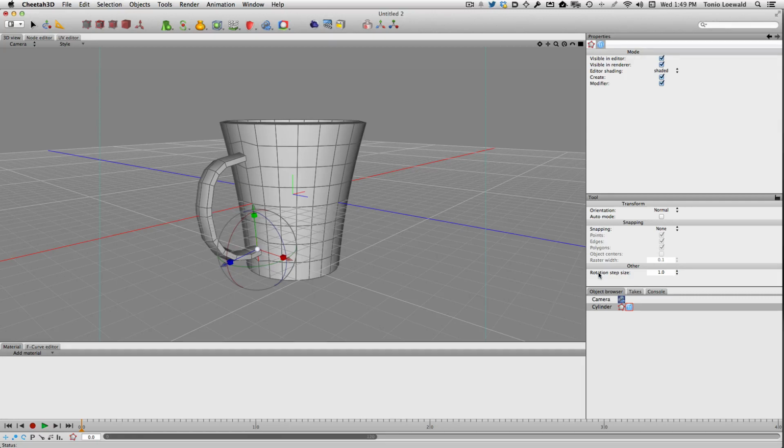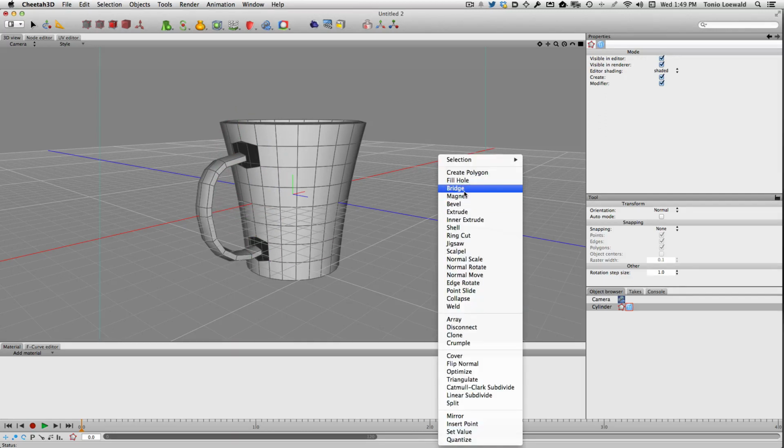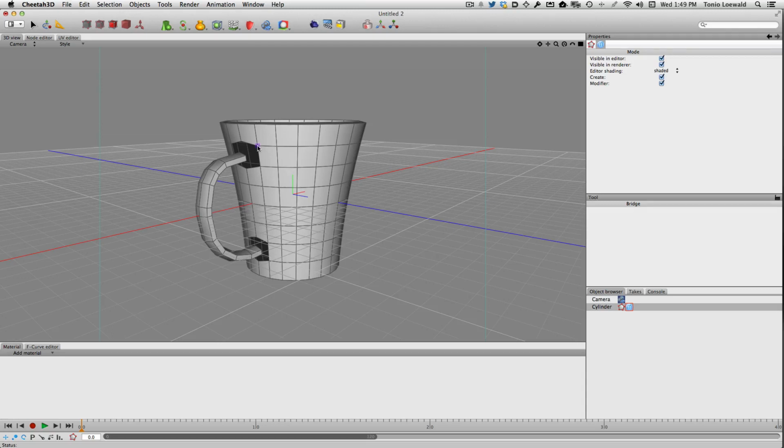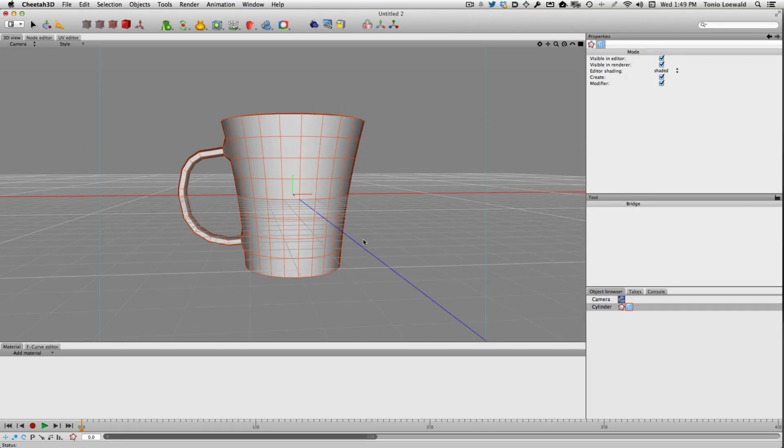Okay. And now I'm going to take the polygon mode, and I go click, click. I'm shift clicking here to get the extra polygons. Press the delete, there's a hole. And now the bridge tool, right click for it. I'm just going to pick this and the corresponding corner I want to bridge to, and I get two nice clean joins. And that is our basic mesh.